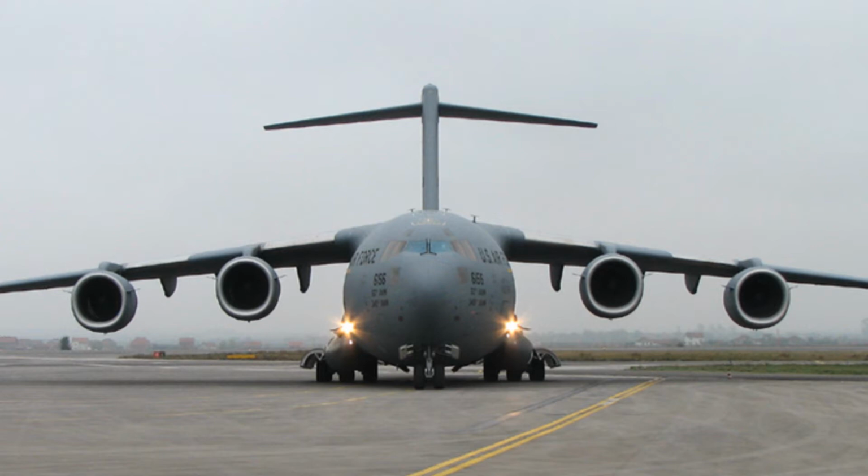So you have this really high stability caused from the up high wings and the T-tail on the back. You're going to start to have a hard time turning and doing maneuvers intentionally. So it's a really stable aircraft as it is. So in order to counter that, you see how they have the wings pointing downwards. That counteracts some of the stability caused by those two other factors.